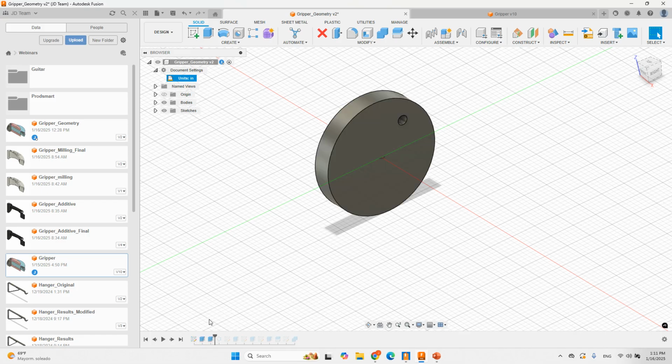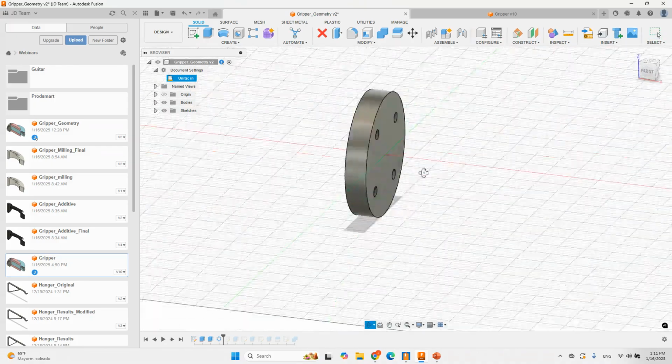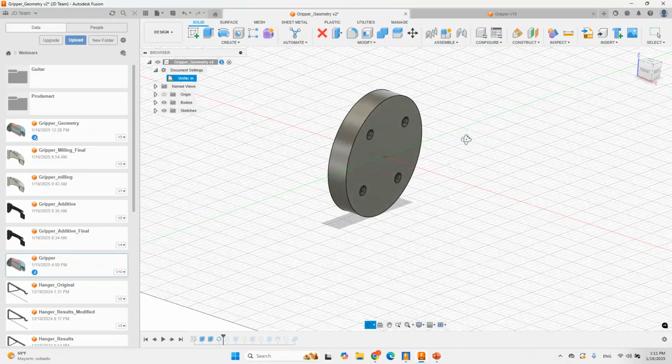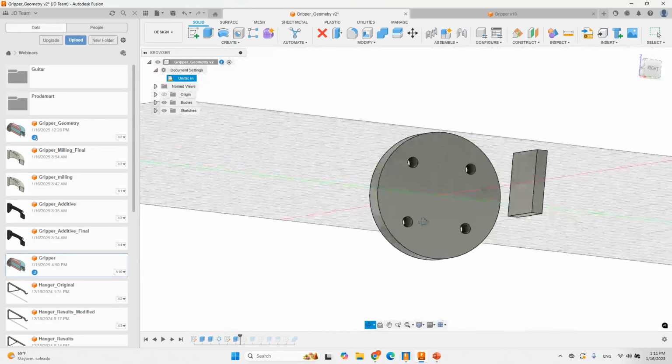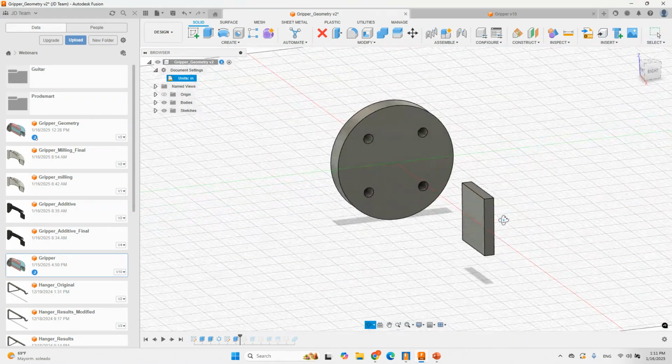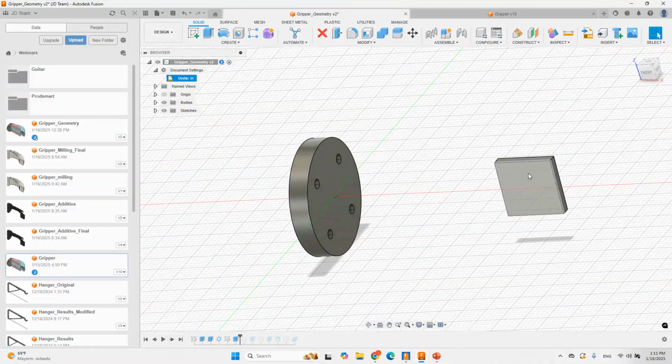First of all, I specified what would be my plate for the manufacturer, where I'm going to attach to my robot. And then I need to tell the software, okay, I want to be able to grab something all the way down here. So this is going to be the region that's going to support the force, where I'm going to assume I'm gripping the part. Remember, this can get as simple or as complex as you want. I'm going to try to keep it real simple.